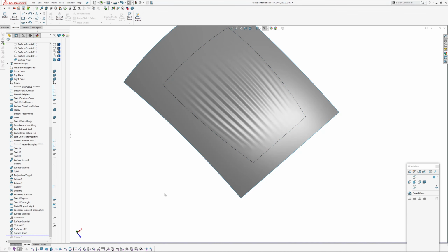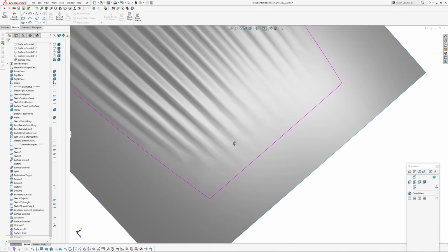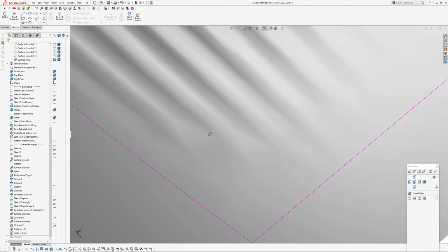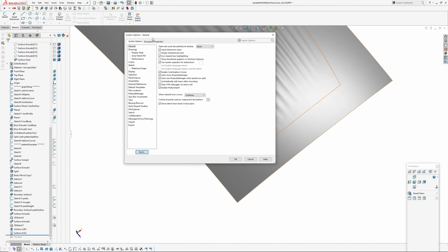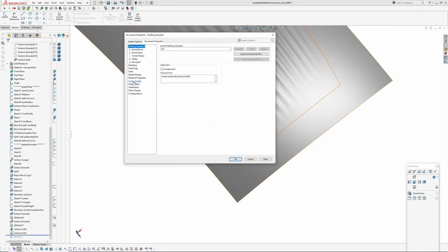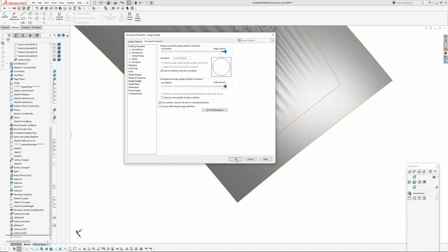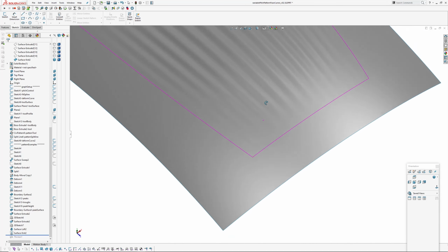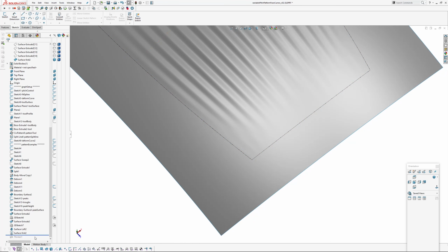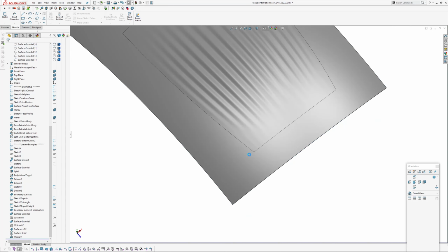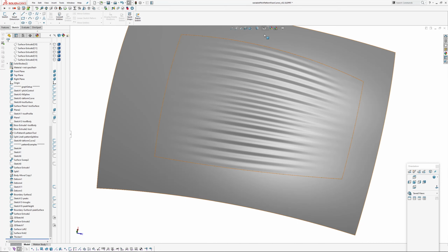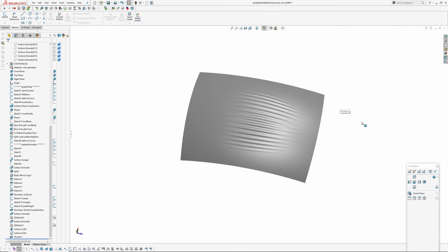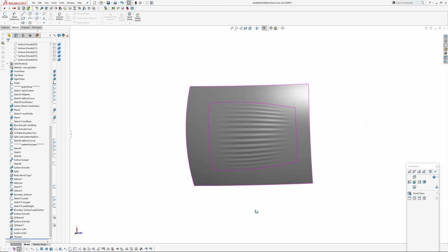Okay, and then knitted that together, and just so I can get a higher, see how the render mesh is kind of cruddy there. Solidworks likes doing that, even though if we go tools, options, image properties, image quality, we're up on high. Now it might update and be nice again. Yeah, there you go. But if I edit something, it will revert to being cruddy. If you thicken a surface, it kind of forces it to hold the higher quality setting for some reason. Okay, so if I turn the edges off, yeah, there you go.